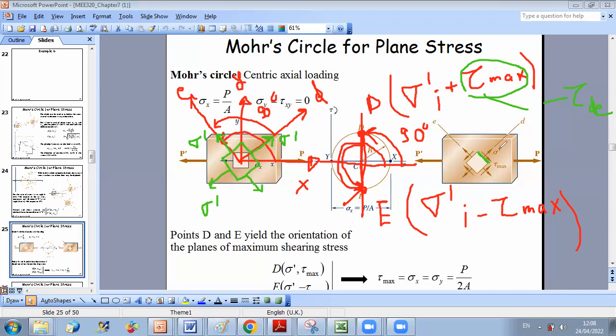And you can see this because if I want to represent a negative shear on this face, I will put it like this, because the unit vector perpendicular to this face is along positive d, and because from Mohr circle the stress at d is negative, this means that the shear should be along minus e. So this is tau max presented on this face.